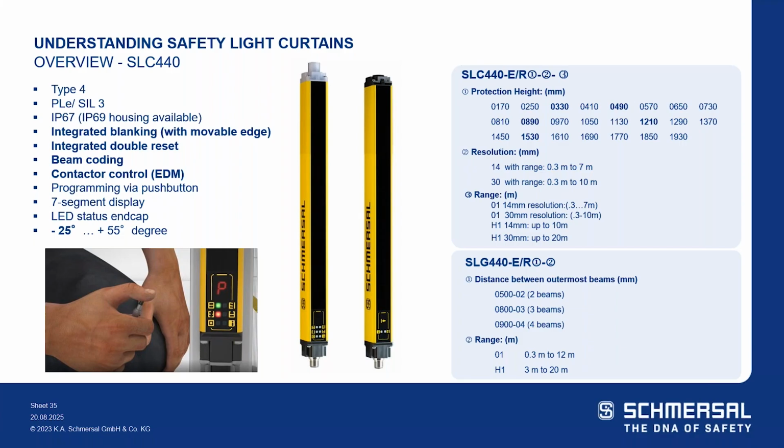So you do not have end-to-end because you do have that 7-segment display, but the 7-segment display gives you operating status as well as error codes. So if you've made a mistake with your wiring, you're going to get error codes. If there's a mistake with any of the transmission of the emitter or the receiver, you're going to get error codes for very easy troubleshooting, as well as some LEDs that are on indicated with symbols on the 7-segment display. And of course, that LED and status end cap that will have multiple colors, and your onboard Bluetooth, which we will talk about in a couple of other slides.